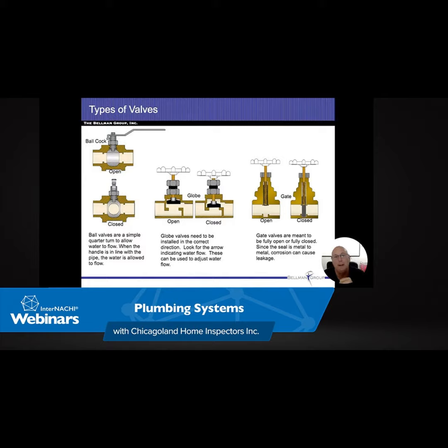So if you ever have a trap that's below the floor from an appliance above, if it's a shower and it's right up there, typically not too much of a problem. If it's a sink that's coming all the way down and putting the trap in there, you're going to be at least 2 feet at that point in time, and you're going to start having some sort of issues. Laundry tubs, or laundry drains, it happens with them quite a bit. They're a little bit higher, so you might be at that 3-foot spot.